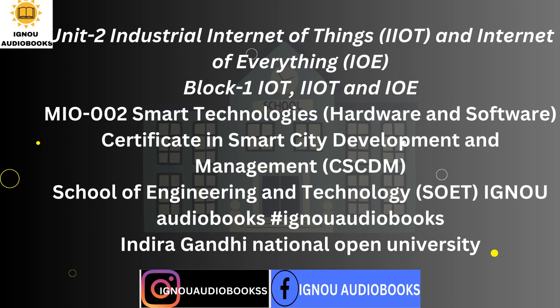Interconnection. The first category is interconnection. There must be interconnection between sensors, algorithms and the operators themselves. This means there must be a human-machine interface, HMI, or a supervisory control and data acquisition, SCADA, system in place that monitors and allows the operators to interact with the process or equipment. This interaction can range from simple monitoring and recording values to complete control and decision-making for the process.